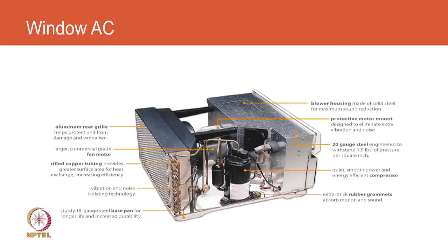And then we also need to take decisions about how to make the flow be managed optimally inside the condenser. Do we have a single circuit going from top to bottom passing through all the tubes, or do we divide it into 2 or 3 or more? That comes out of an analysis of the optimum heat transfer coefficient and pressure drop. There is a penalty, which is pressure drop. If we have just one circuit, we will have a higher pressure drop, and therefore, we will lose some of the power of the compressor in just overcoming that, and that will have a penalty on energy efficiency. At the same time, we will have increased heat transfer because of higher flow rates.